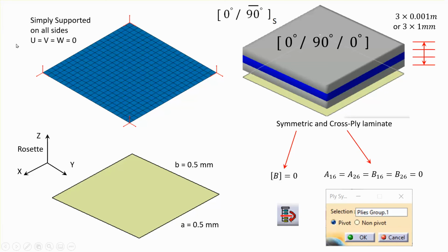Now, the other comment that I have to make is, in composite problems, try not to use finite element symmetry. If you're not absolutely sure that this mode is going to be a symmetric mode, or that the calculation allows you to take only 1/4 of this geometry, try not to use it, because sometimes it's obvious, sometimes it's very difficult to see. So I use the entire model.